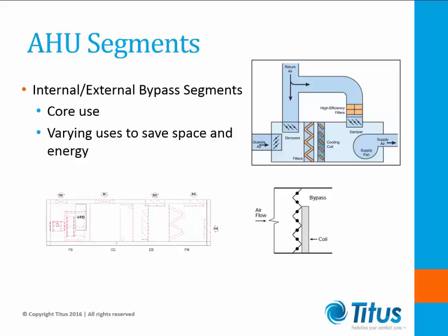Also worth noting, pressure drop of the cooling coil will increase with latent capacity. A 100% sensible coil has a lower air pressure drop for the same face velocity as a coil with latent capacity. The reason for this is that the air tunnel through the coil is decreased due to the condensation between the fins. The manufacturer should provide selections at different entering conditions to determine dry and wet pressure drops. The designer will also need pressure drops across the bypass at different airflows to verify the need for a cool face damper.